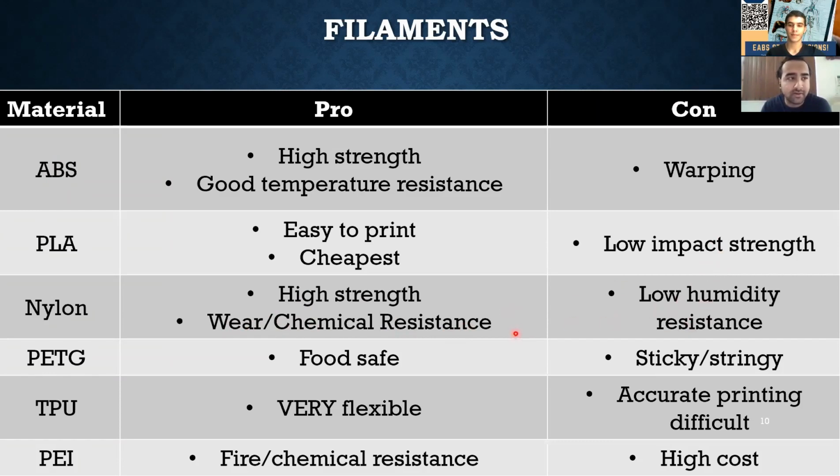So much so that if you have any sort of nylon material that you're trying to print with, and you don't put it inside some sort of desiccator, for example, when you try to print with it, you'll hear bubbling and cracking in your printer because there's actually water inside your nylon that is bubbling up and expanding and leaving your filament, and that can cause so many problems in your prints. So you always have to make sure you store nylon in a desiccant bag and away from any air or moisture. Next one is PETG. So the nice thing about PETG is it's food safe.